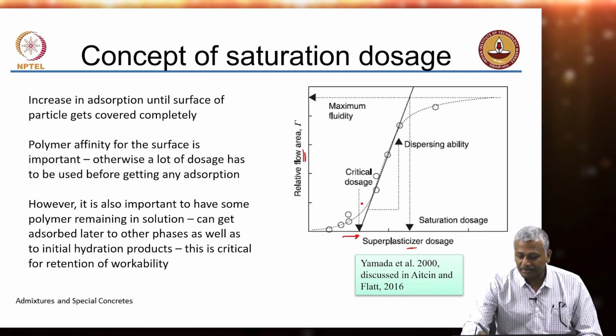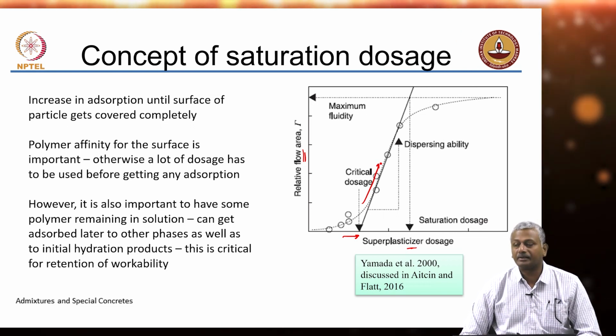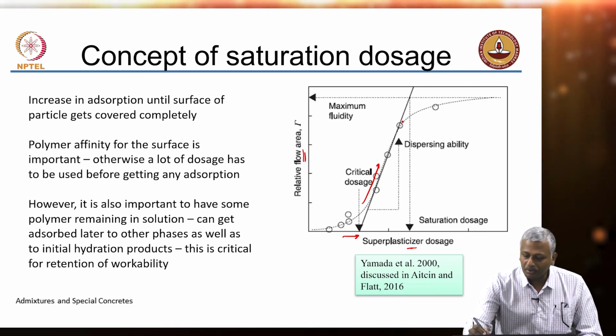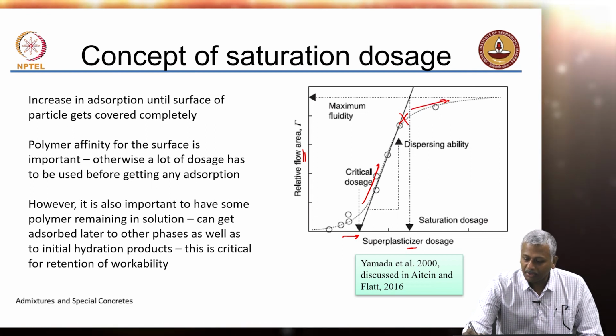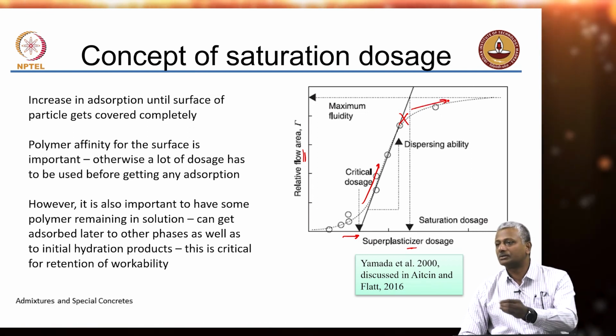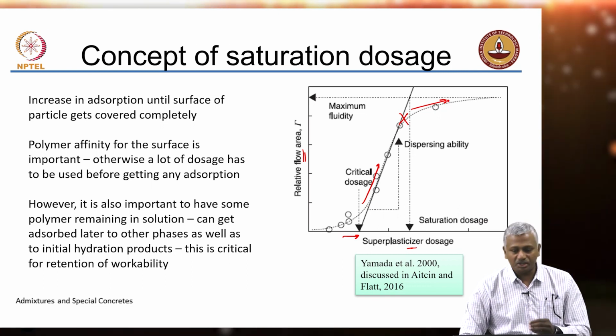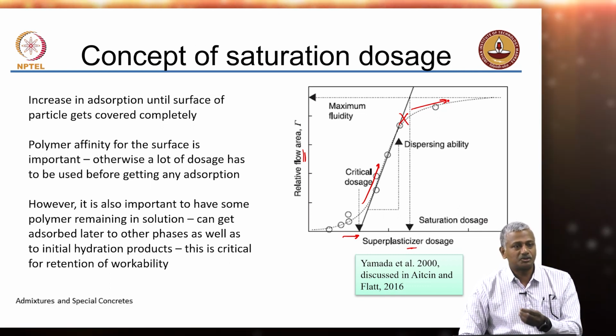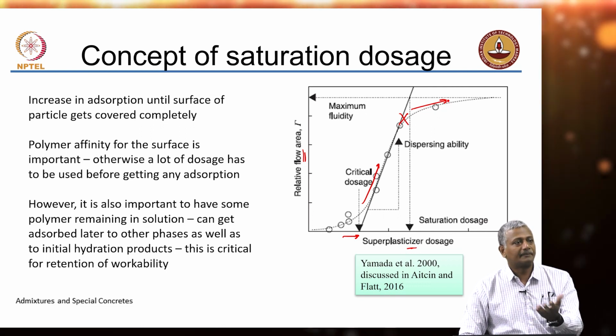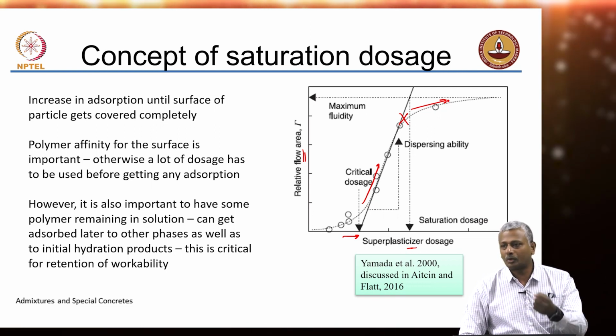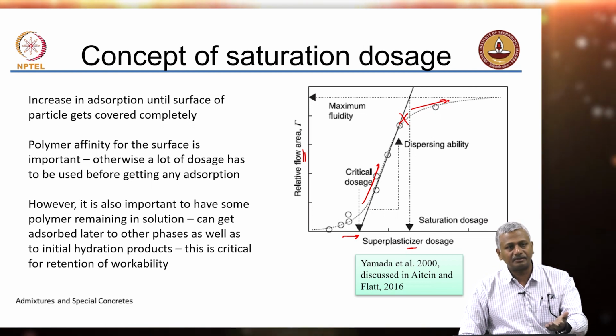Beyond a certain point, it seems to go up quite critically. But beyond another point, you are probably not going to see much enhancement of your workability. That means you are reaching a level of saturation, where your concrete has probably no extra impact from the additive that you are putting in.